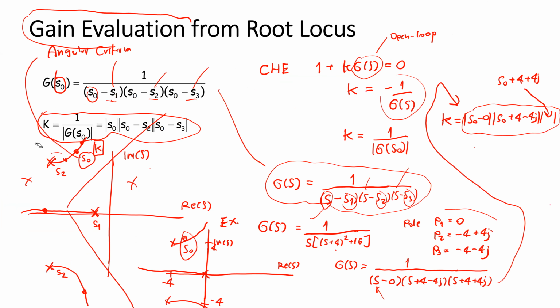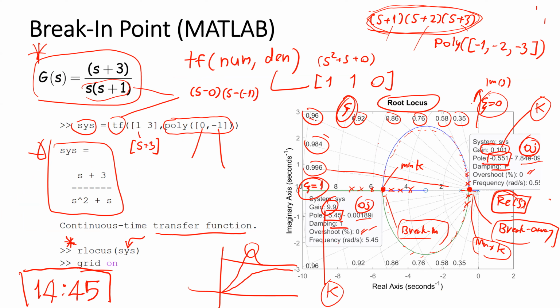We see this and the damping ratio, the constant damping ratio line is the radial line drawn from the 0, the origin. And another thing that is important is the angle that the constant damping ratio line makes with the horizontal axis, the negative real axis. The cosine of this angle is equal to the damping ratio.